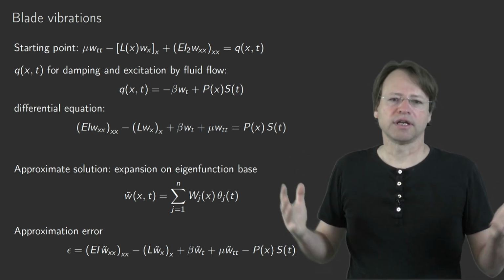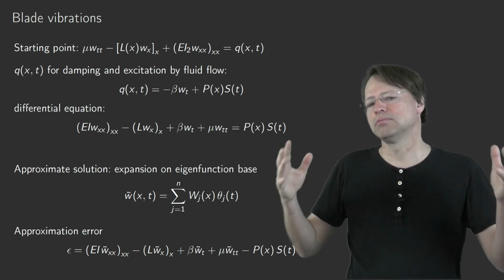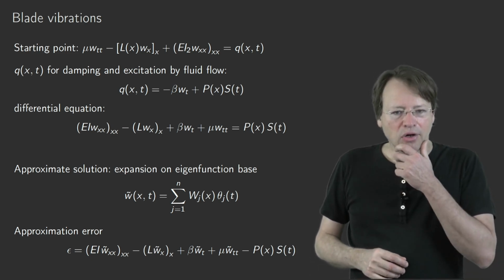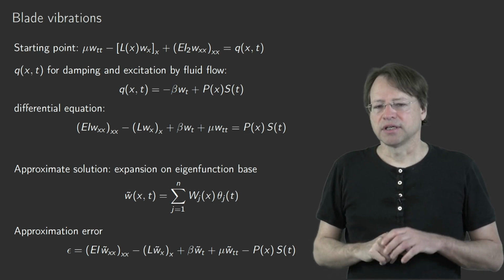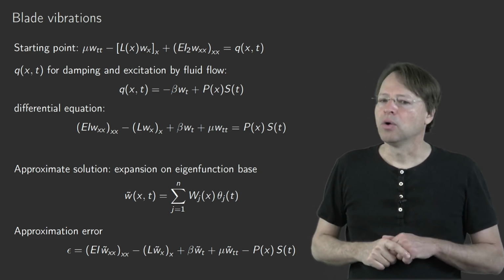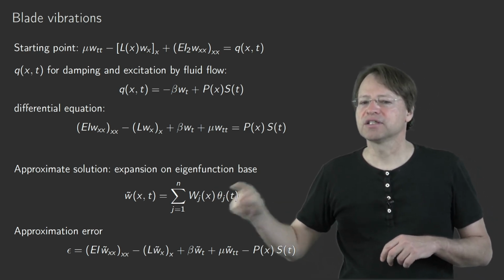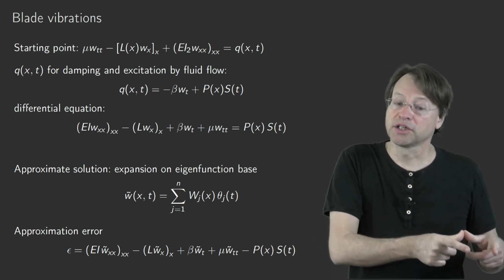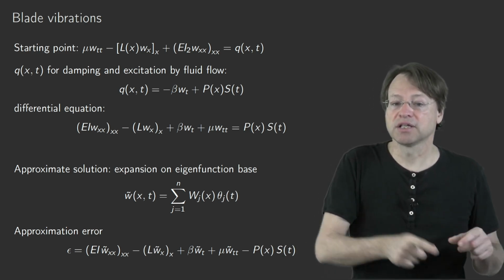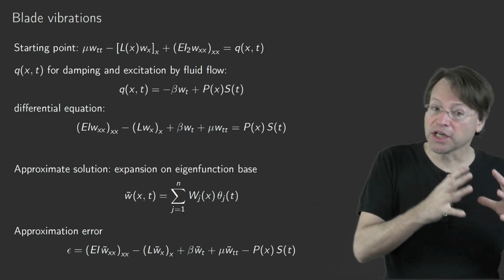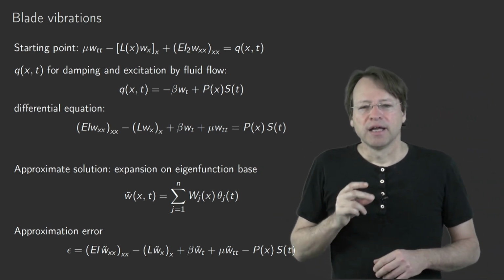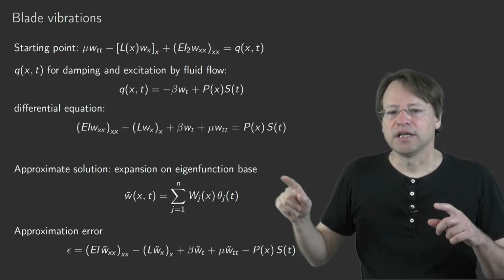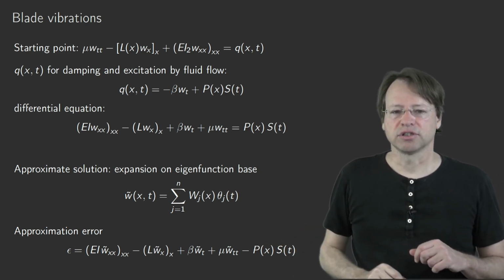You could, for example, take harmonic functions or polynomials or whatever. But if you think of what you did here in dynamics, then why shouldn't I recycle these eigenfunctions again and use them also for the projection on the functional space, as the basis vectors of the projection space? That seems to be very clever, right? Because there are orthogonality relationships between these eigenfunctions.